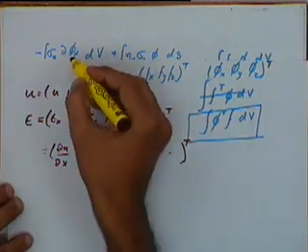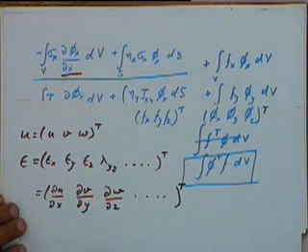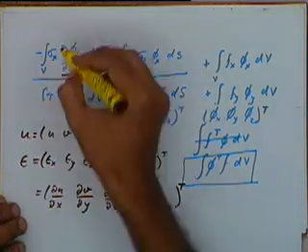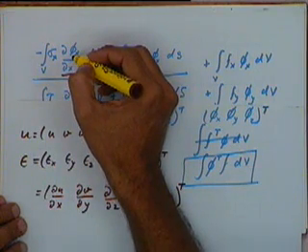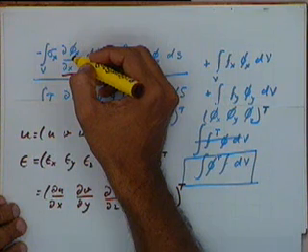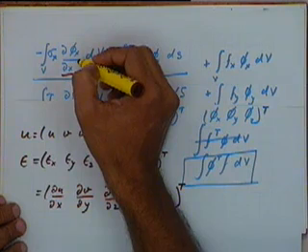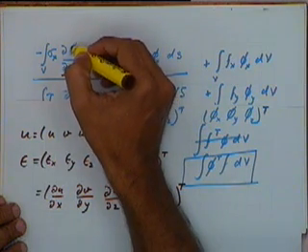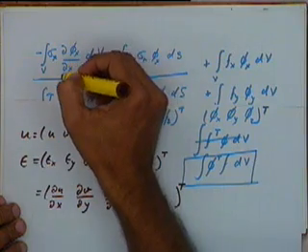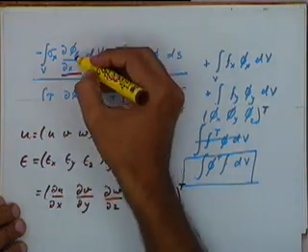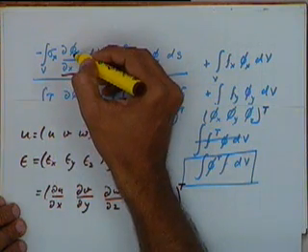Okay, now here we have got a term on phi x, that is del phi x by del x. And we also said that the phi, that is the weights that we are giving, are consistent with the boundary conditions. That is one of the constraints that we had in the Galerkin's approach. So we can effectively say that we can take this phi to be equivalent to a displacement, and del phi x by del x is the strain in the x direction that will be there in the object if this phi was given as a displacement.